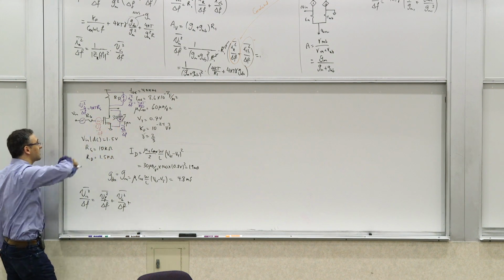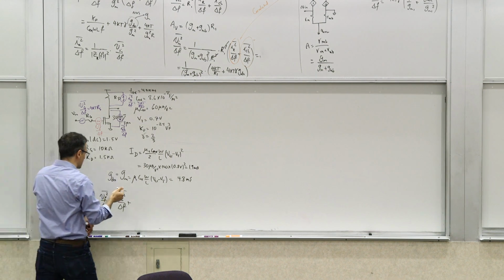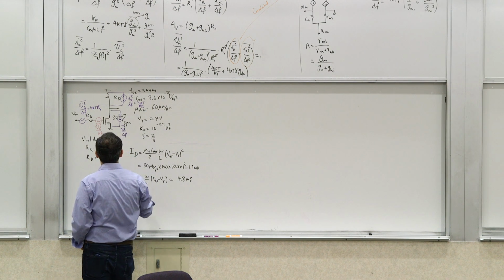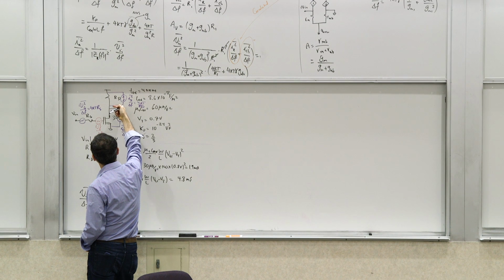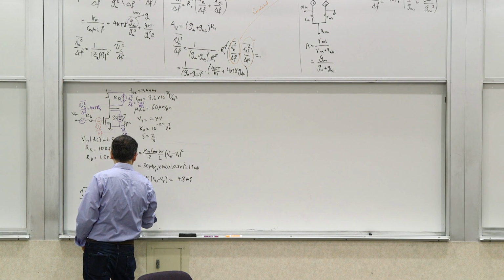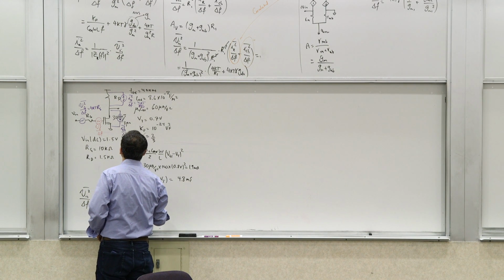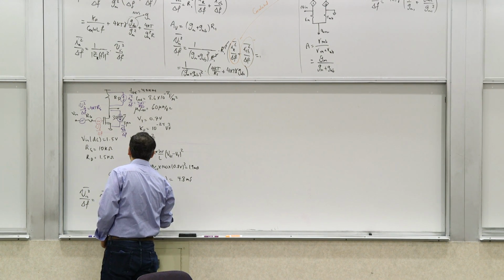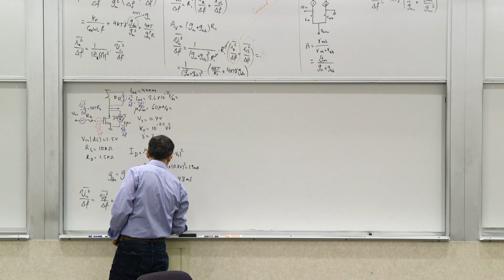now you have these 2 noise sources that are injecting current into the output node. What's the resistance on the output node? R1 or Rd, yeah, in this case it's Rd. So they're going to inject into this to produce a voltage across Rd, and then you need to divide it by Gm Rd, right? So you divide by 1 over Gm squared, because Rd will cancel. 1 over Gm squared times Id squared over delta F plus I channel squared over delta F.